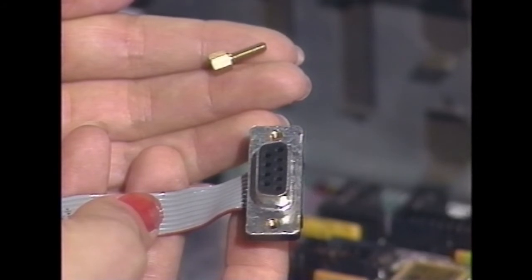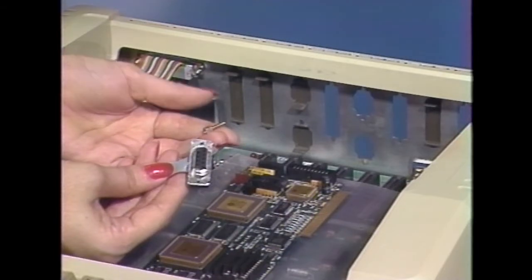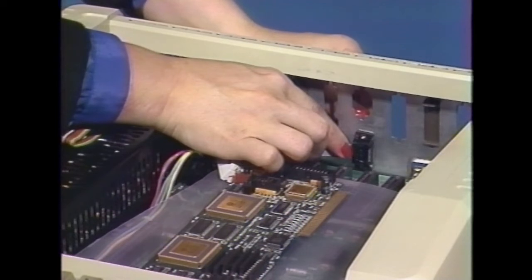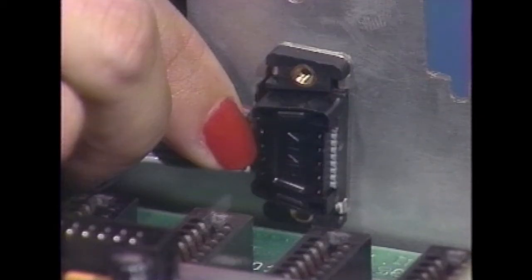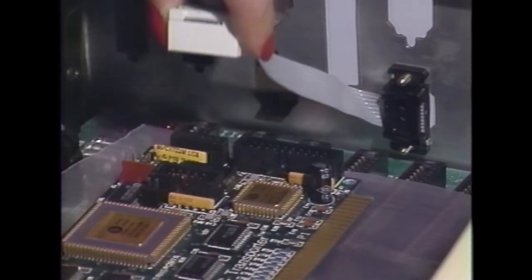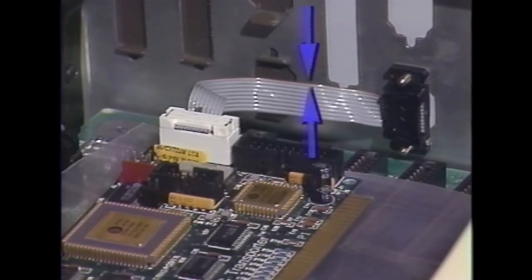Locate the digital RGB adapter cable. It is an optional cable and is not included with the installation kit. Remember, the cable may have a slightly different appearance, but its installation and function will be the same. Find an unused small-sized opening in the IIe's backplane. Secure the female connector in the IIe's backplane using the screws provided. Now, attach the male 10-pin connector to the female 10-pin connector on the transporter as shown here. The cable stripe must be toward the top edge of the PC transporter.